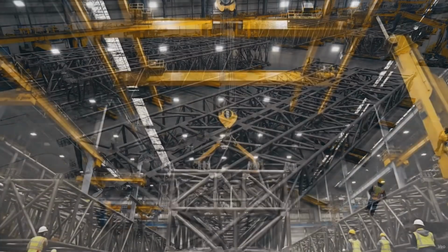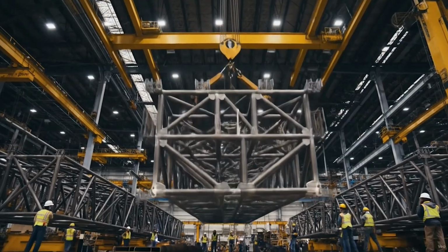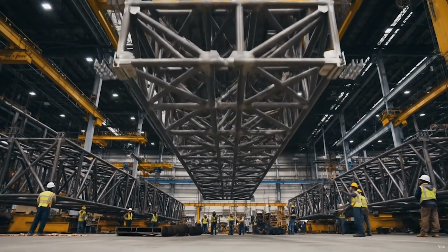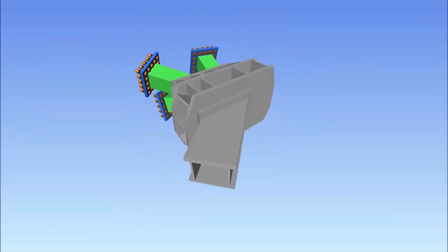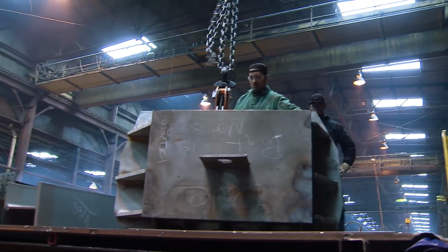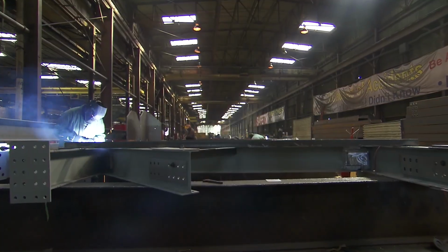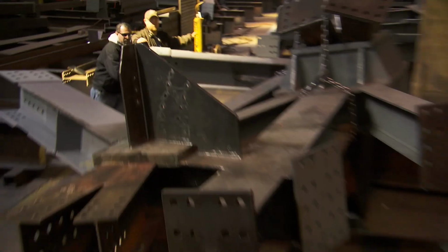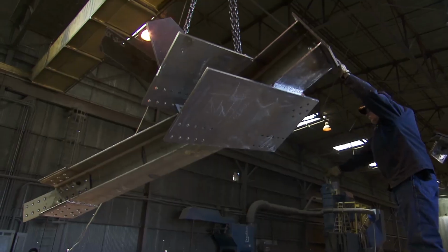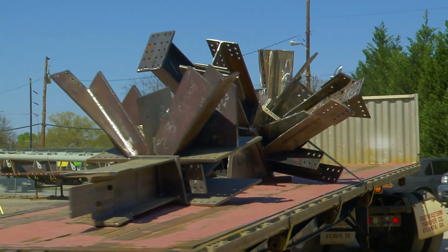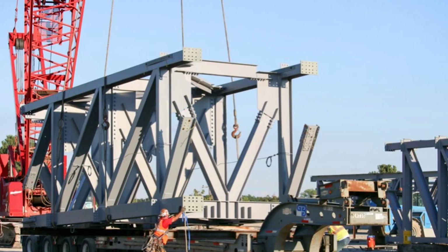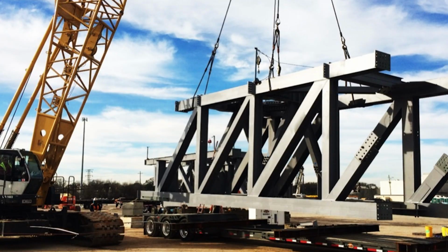The components of the megatrusses were prefabricated off-site at 15 different manufacturing facilities. The total weight of all the truss members amounted to approximately 27,000 tons. The largest individual component measured about 67 meters in length and weighed up to approximately 800 tons. Due to the immense size and weight of the components, it was not feasible to transport them to the site as complete units.